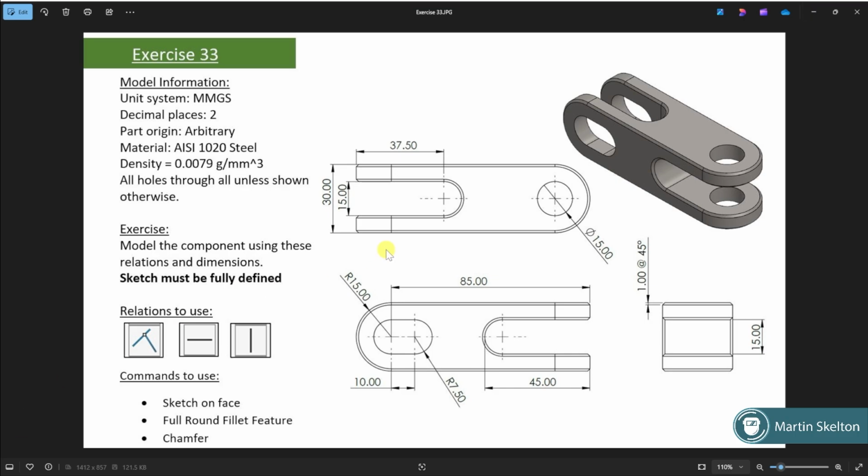for learners. How do I know what plane I'm going to draw on? Now there is a perfect question that I get asked many times. How do I know what plane my drawing starts on? The best answer I can provide for that is usually draw on the plane that has the most information to create the model. That is in general. There's often times that you might have to pick the plane according to another parameter or with another restriction. This time I am going to start on my front plane.